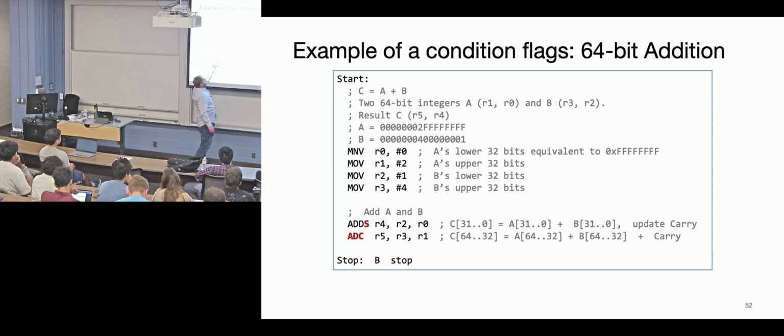And then you do the add, and you set the ALU flags, and then the instruction here, add with carry, looks for that flag, and will take that carry bit and do that task for you. So it will do it correctly by setting that. Now you don't have to set it. In this example you would, or else it wouldn't operate correctly. There's no advantage or disadvantage in the sense. It's just if later on you're going to need that value for something.